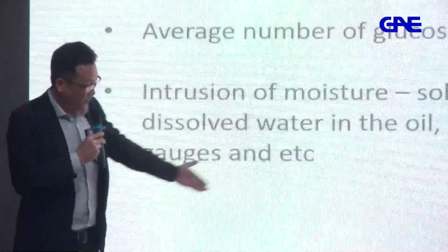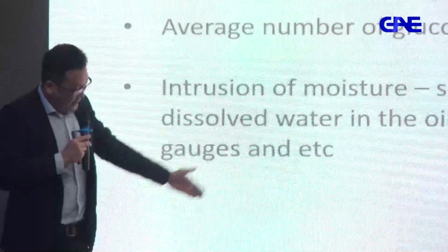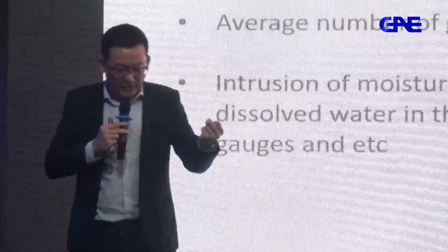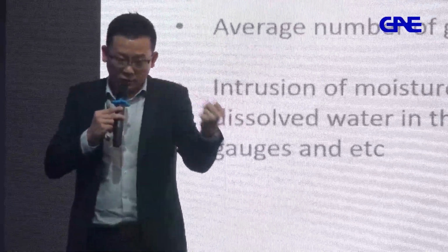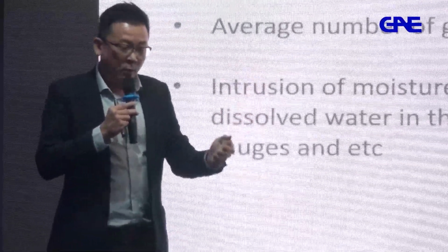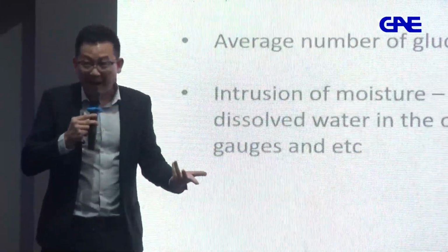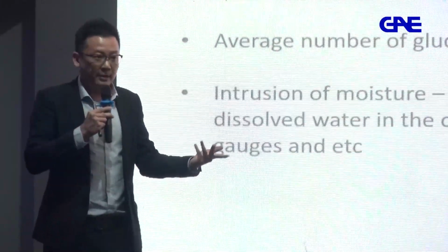The chain itself, all this 1200 DP, is a very strong mechanical chain holding everything together, making the strength of the paper. So it can withstand mechanical stress, electrical stress, especially arcing, all these things occurring inside the transformer.